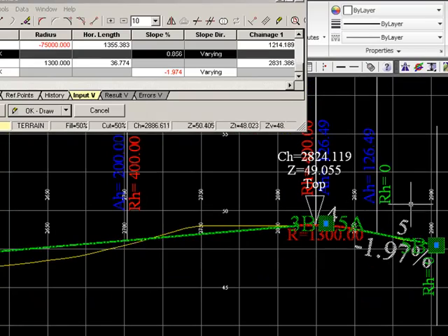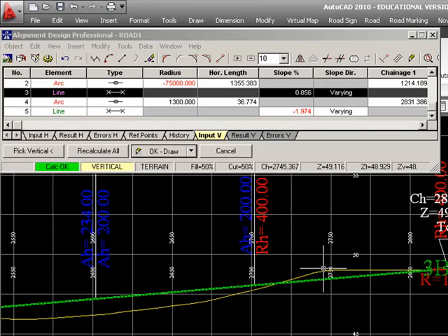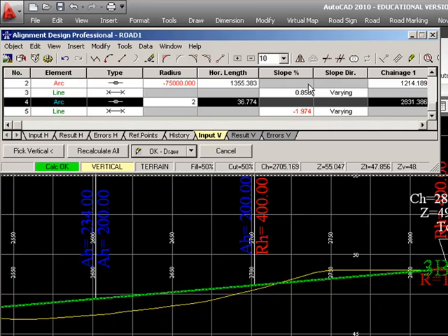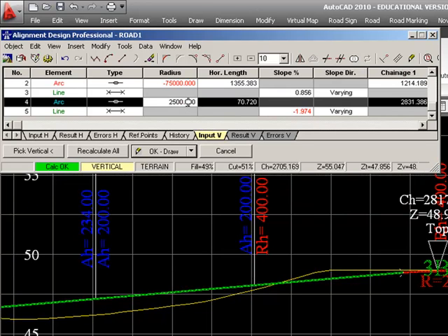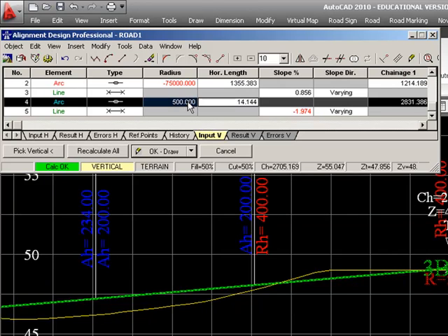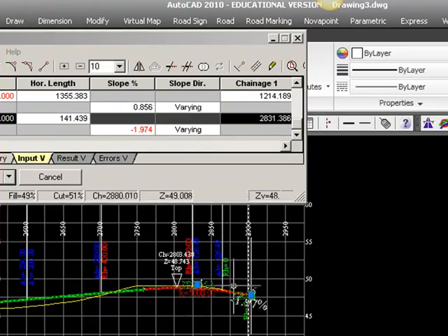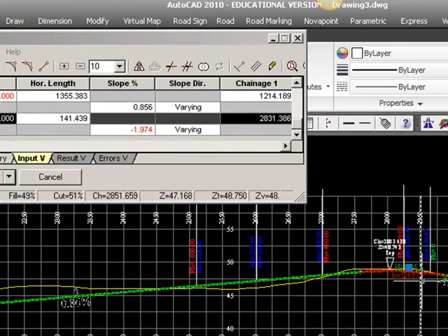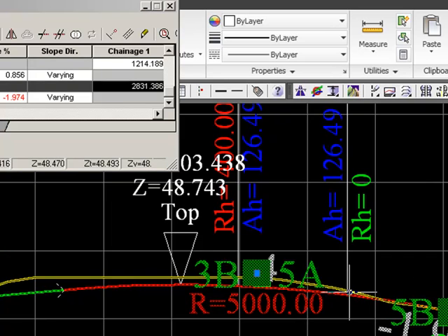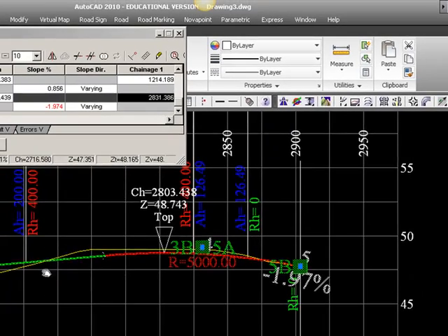Now this is a very small radius used on the existing road, and that may actually be the case, and you should now consider whether you want to change it to make it better. I could maybe put in a larger radius. I know I have to do some changes on the existing road then, but it is a bypass, and I would like my road to be smooth and good looking in the future, so I might as well offer the cost that's needed to make the connection good. So something like this.